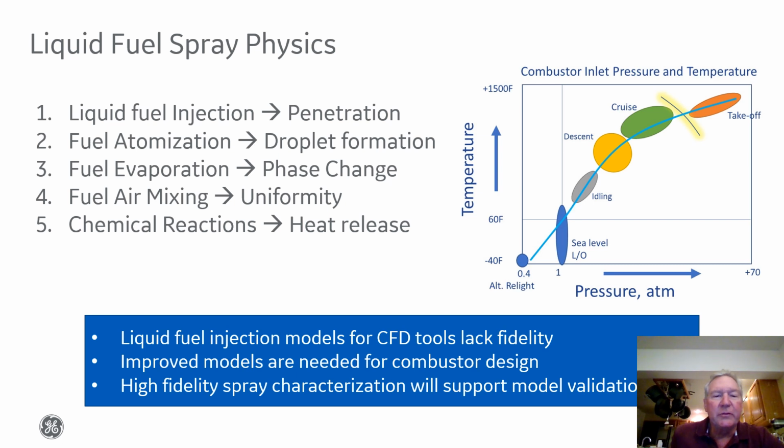So liquid fuel spray physics are very complex. It's one of the more complex aspects of the physical processes that occur inside the combustion chamber. So we've just pointed out a few processes. It starts with the fuel injection, the jet or liquid fuel penetration in an airstream, fuel atomization, droplet formation, then subsequent fuel evaporation, a phase change.